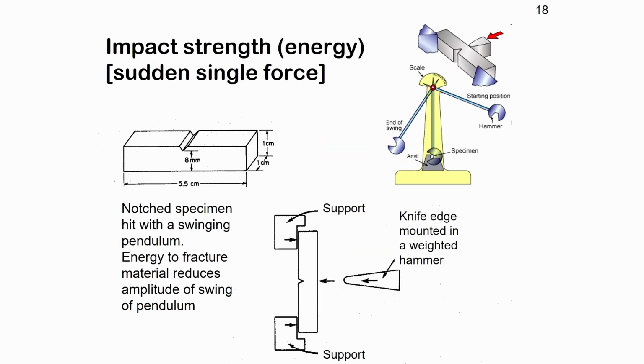Okay, we've just mentioned impact. Traditionally, engineers like to use the so-called Charpy test. It uses a beam of material with a notch, creating stress concentration, so we know exactly where the beam is going to break. We use a pendulum raised to a great height, and just let it go. And the impact will break the beam specimen.